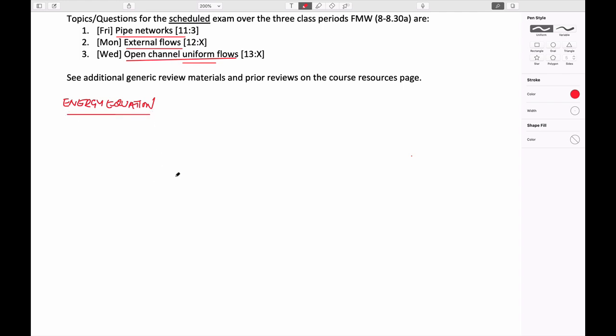And you know that if you look at the behavior of flow from one tank to another, with big tanks flowing from one to another in this particular case, then you would expect some drop in head between those locations, which we can call, for one pipe anyway, H sub L.